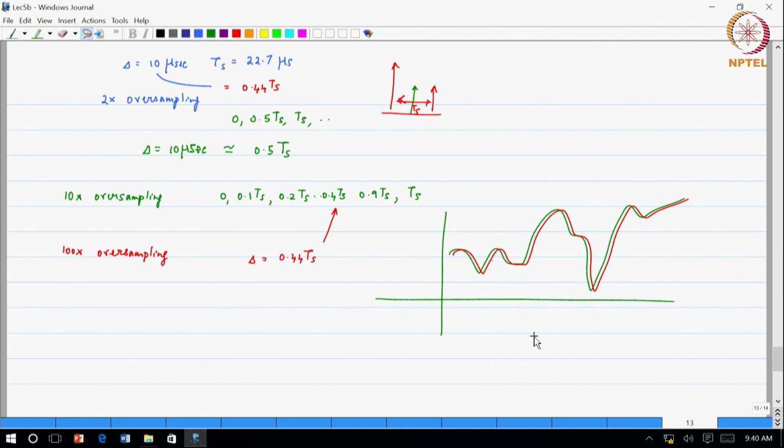Of course, you need not go down to the lower sampling rate, because the oversampling actually helps your D to A conversion. So you can say that anyway I want to do oversampling to do a good D to A conversion, but in principle this is what we are trying to do. So you have actually introduced the effect using the multi-rate part. You can go back to the original sampling rate if you want to, or you can retain it and then go to the D to A process at the higher sampling rate.